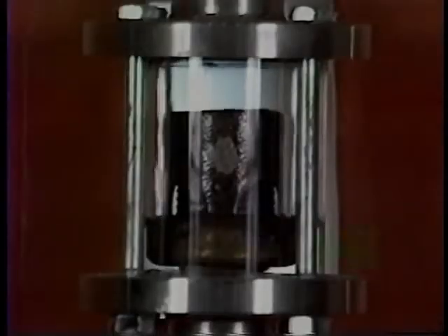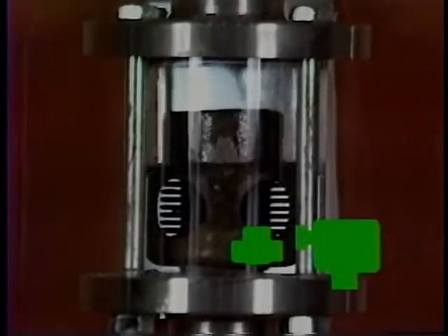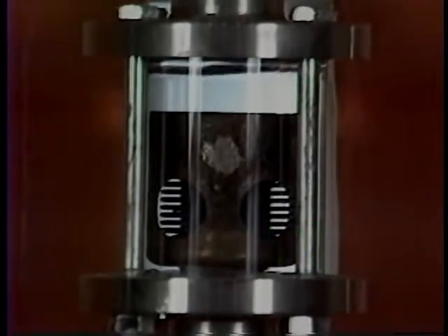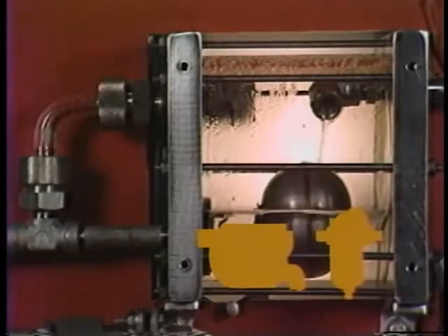One of the first evaluations should concern the amount of live steam lost through the trap when it's new. All trap types condense some steam due to thermal radiation, but live steam is discharged from some types even when new because of the way they are controlled or sealed. The water seal prevents live steam loss through the IB and the primary orifice of the DC. Disc and bellows traps prevent live steam loss by closing in the presence of steam or condensate near steam temperature. F&T and DC traps pass live steam mixed with any air they vent.